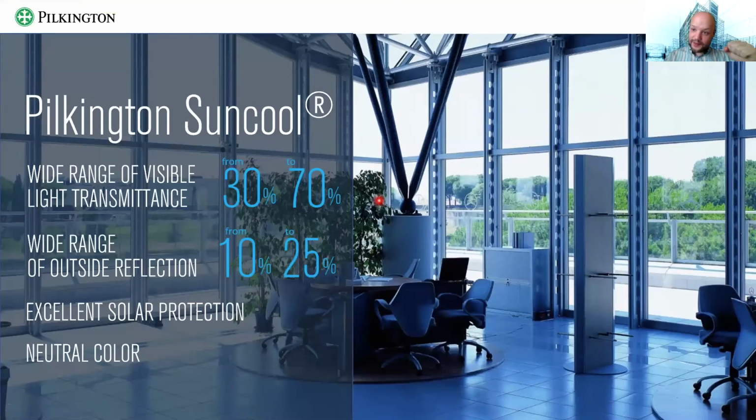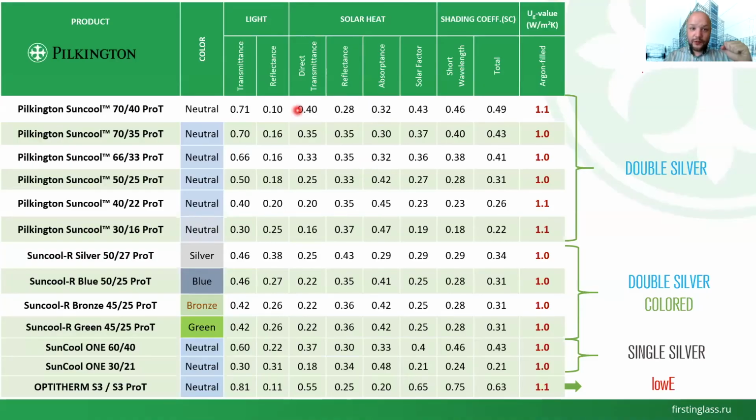And that flexibility of the soft coatings and the layer combinations gives our product range a wide variety of characteristics. For sun-cool, the range of light transmission is from very high to very low. You can get colored versions of the glass if you want some color. For normal neutral colors, the light reflection is usually from very low to medium. If you want a very high reflective glass, yes, the colored versions are ready to provide that.